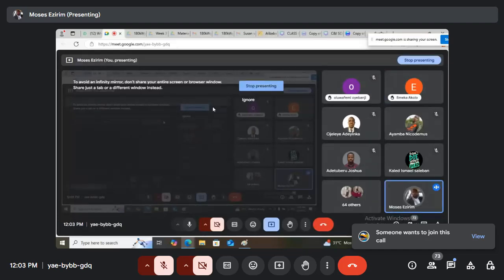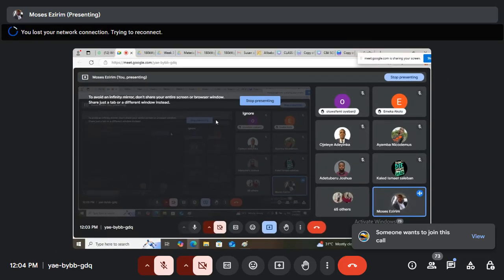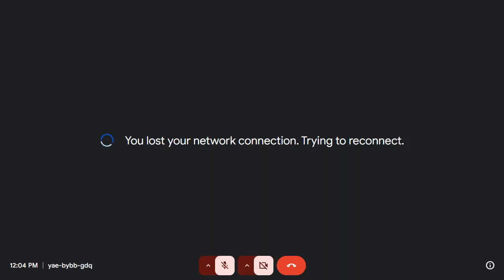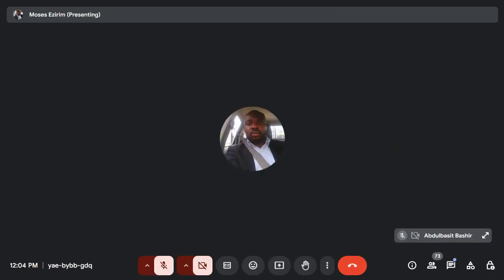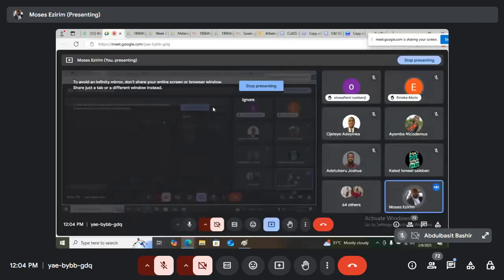In Europe, where the temperature is -30, -20, you need to factor that in as well, because in Europe there is what we call maximum string voltage. That is the standard. Every country has a maximum for every string, 1,000 volts. It's the law, the regulation. You must know it. Once you know that, when you are designing, you have the string voltage, then you need to factor in the maximum and the minimum. We are going to get there.